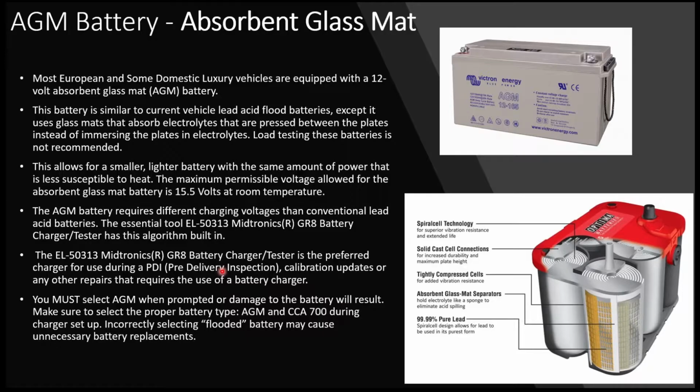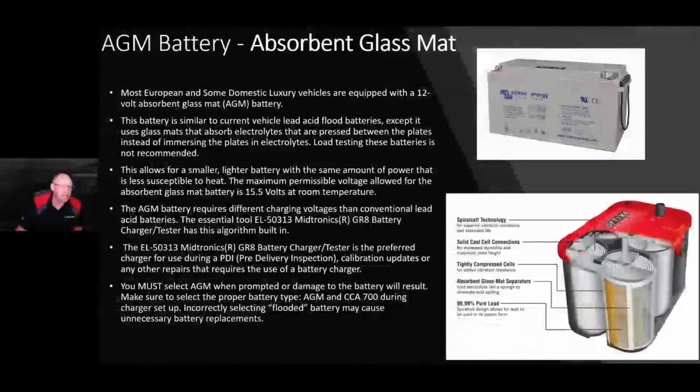When you charge an AGM battery, you have to charge it with a charger that has a specific mode for AGM. If you charge these batteries with something that is not designed for that specific battery, because of the algorithms at which it charges, you'll destroy the battery. You'll burn it up in most cases.